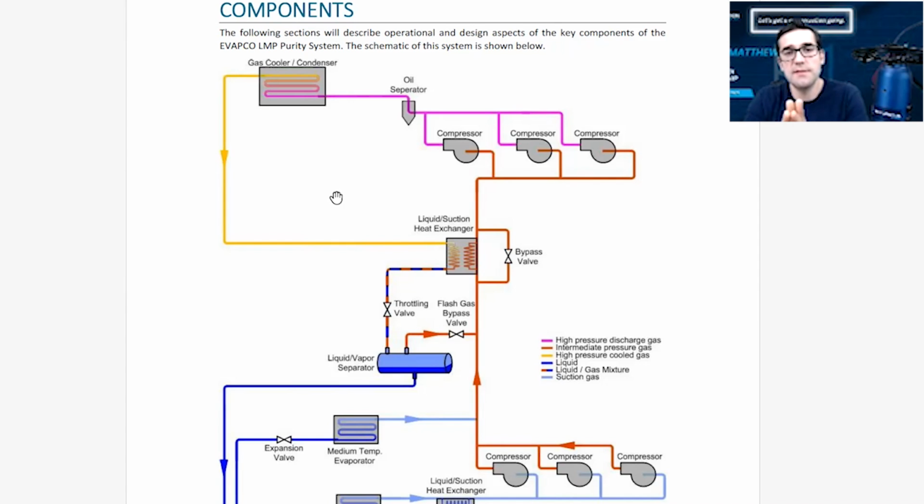Well, the big thing is when I first started looking at CO2 back in 2014, 2015, the gas cooler condensers were made of copper except the header. And that's still a lot of ways it is done, because that 3/8, that really tiny pipe, has a thicker pipe. The durometer rate, I don't know if durometer is the right word, but the thickness of the pipe is thicker at 3/8 than when it's 7/8 or 1 inch. So it can handle a lot more pressure.